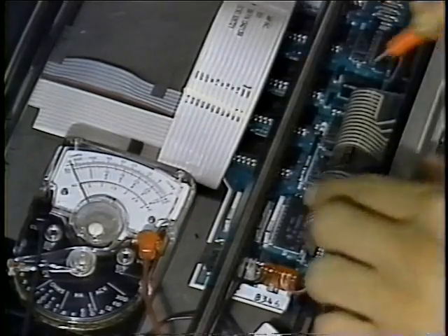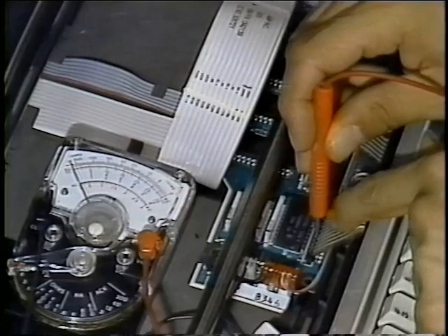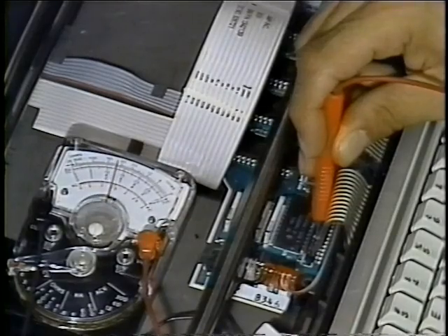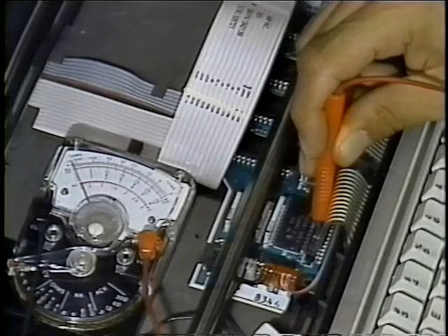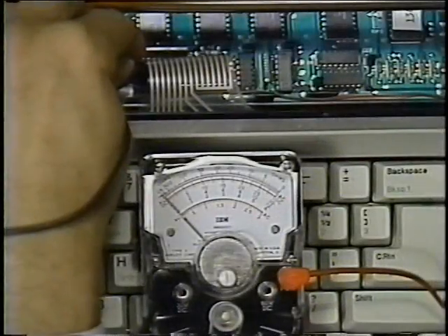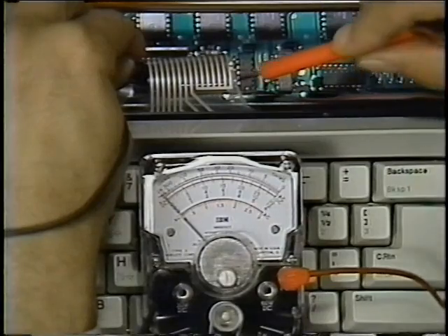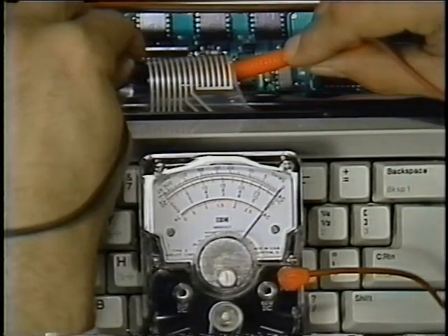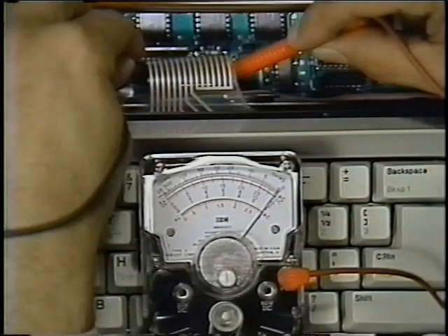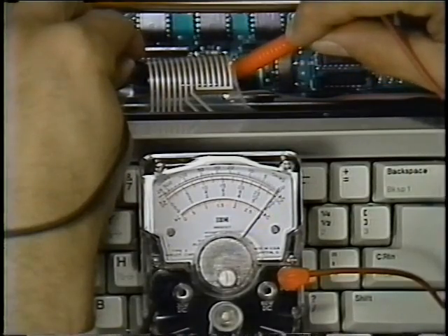To check a drive line, probe the J1F connector pin for that drive line. When a key button that uses that drive line is pressed, the meter should read more than 1 volt DC and less than 1 volt DC when no key buttons are pressed. To check the keyboard ID lines, perform a continuity check from pin 9 of the J2F connector to pins 10 through 15. The meter should read less than 100 ohms on the ID lines that do not have holes punched in them.